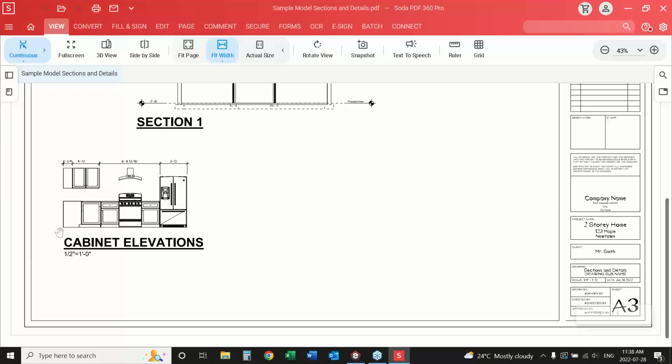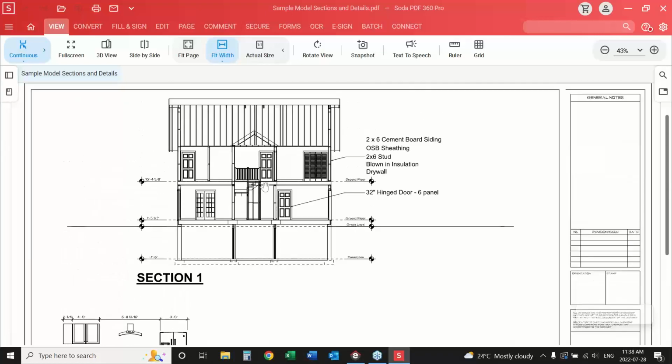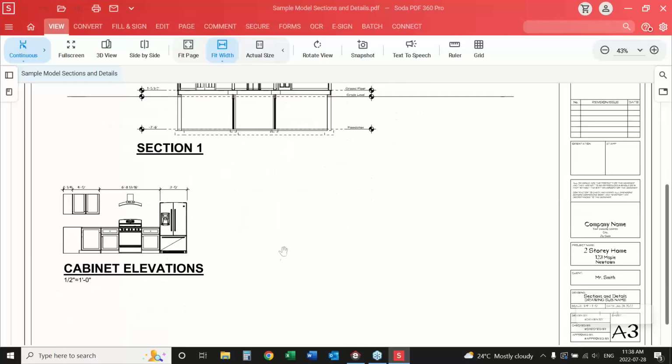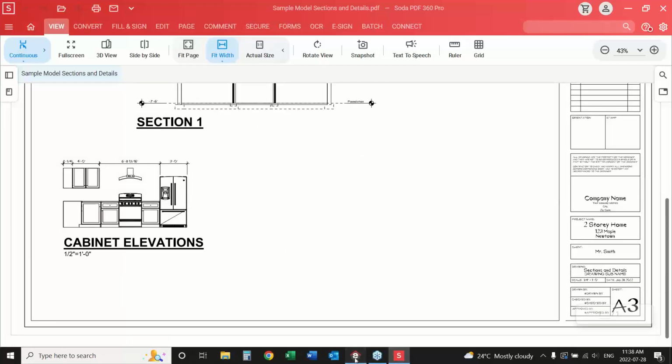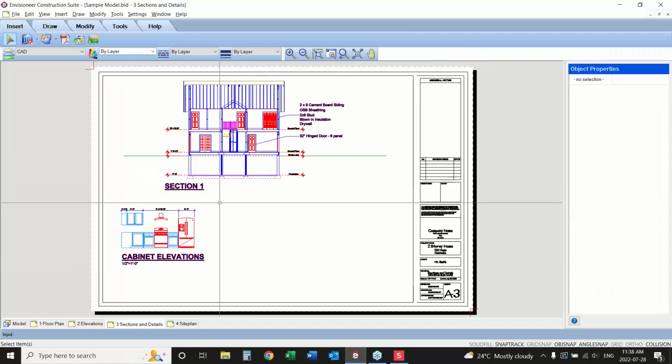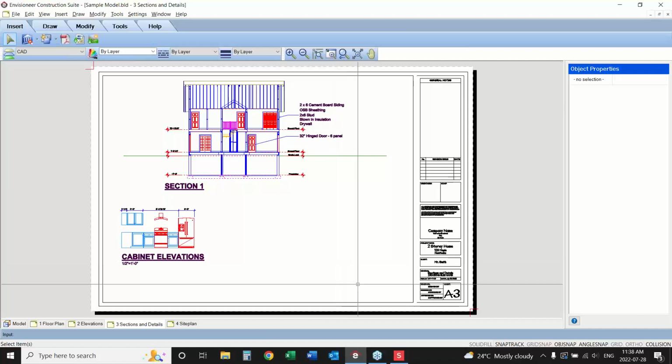And if you laid down a scale on top of that, this would scale correctly, as with this. You'd use a 1/4 inch scale on here and a 1/2 inch scale there, and they would print correctly. Because when you're printing the sheets, you're telling it the scale that the entire sheet is. The entire sheet is a 1/4 inch environment, and you've printed to that. So it prints it to a 24 by 36 inch piece of paper.